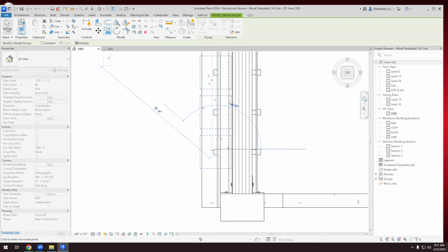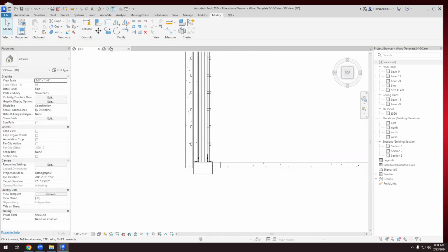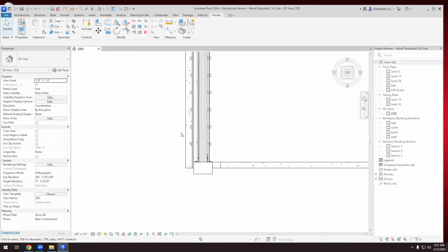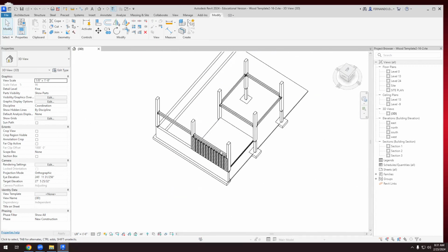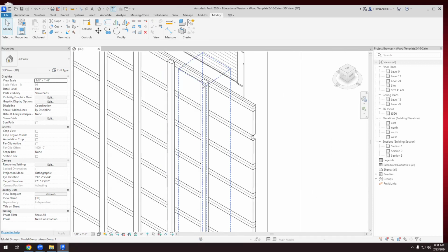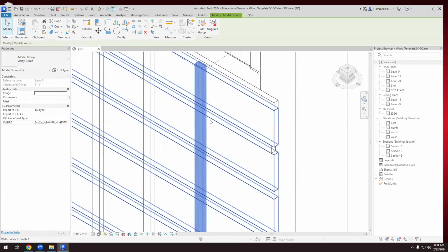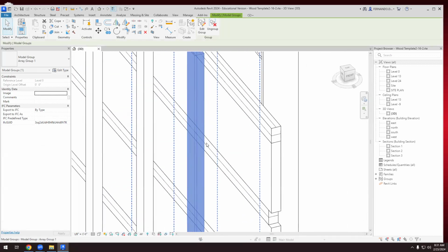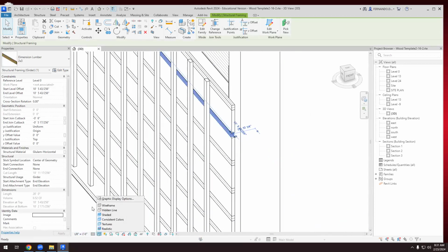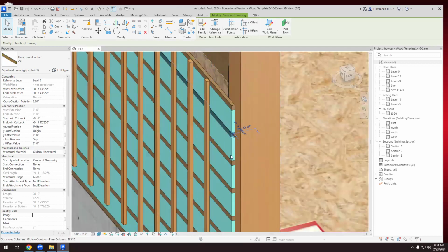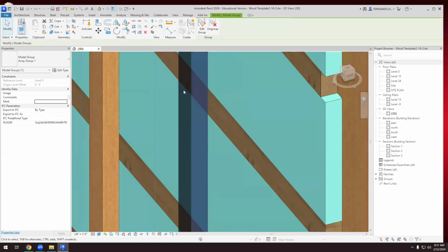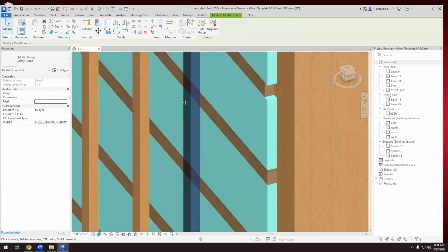Here that I can put up. Yeah, so I need this grid. So those vertical elements are nailed not to the thermal insulation, they are nailed to the horizontal structural element. If I use realistic colors, so this is made of wood, this is made of wood, and the nail will be here, connecting these two wooden elements.